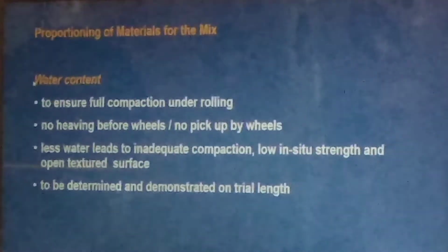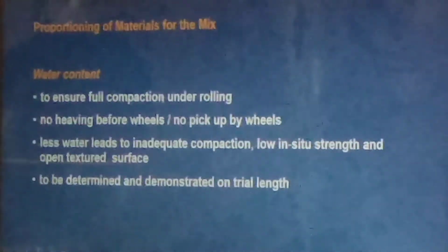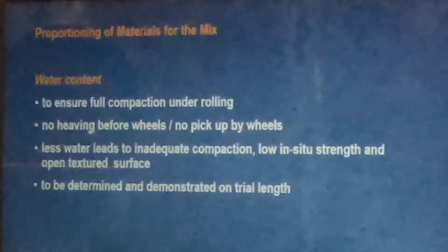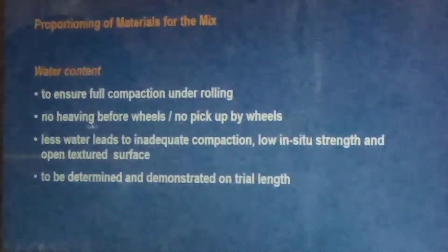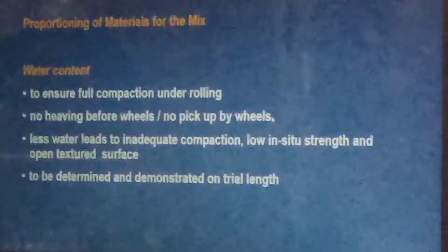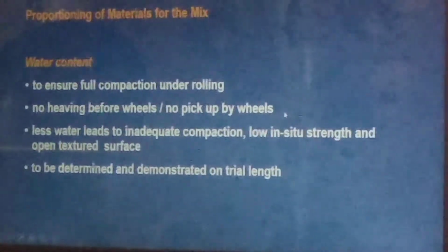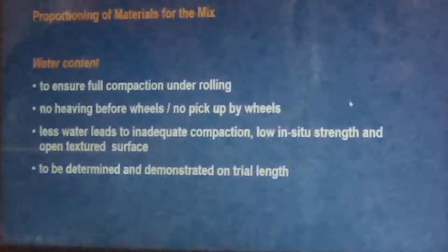Now look at the water content. Water content is to ensure full compaction under rolling, and no heaving before the wheels or no pickup by the wheels during the compaction of dry lean concrete using the rollers.